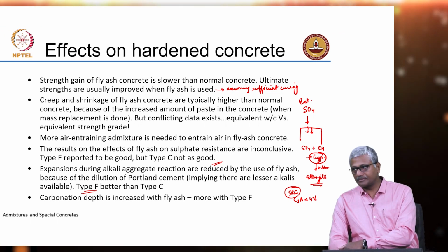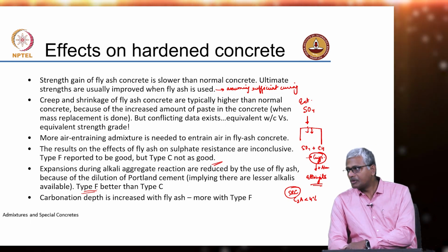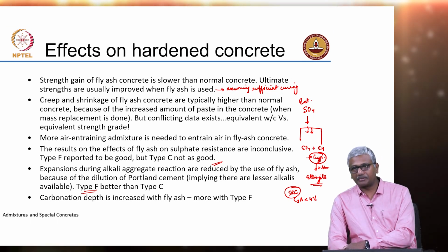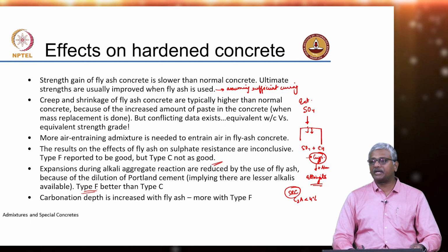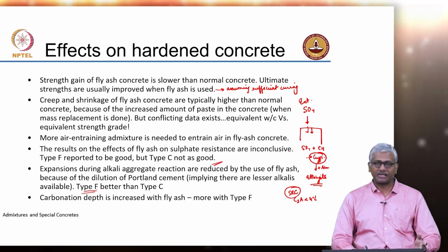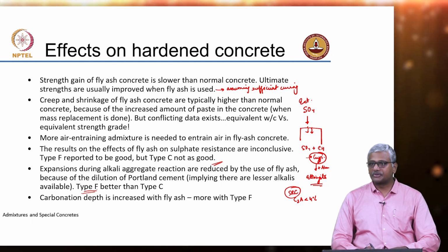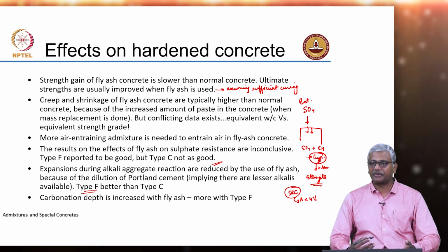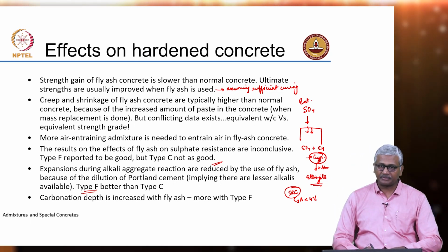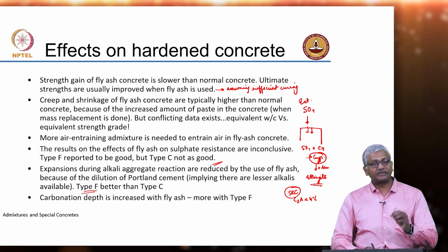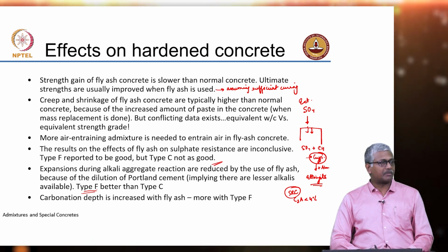But in concrete, which uses cement, what will this do? You start reducing the pH of the concrete because you are consuming the available lime and converting that into calcium carbonate. You are reducing pH of the system, that leads to corrosion of your reinforcing steel. Now, in plain cement, there is a lot of calcium hydroxide available. So, the formation of calcite will keep happening, calcium carbonate will keep happening. But in blended cement, you do not have as much calcium hydroxide available. So, some other calcium bearing compounds will now start having to react with this carbon dioxide.